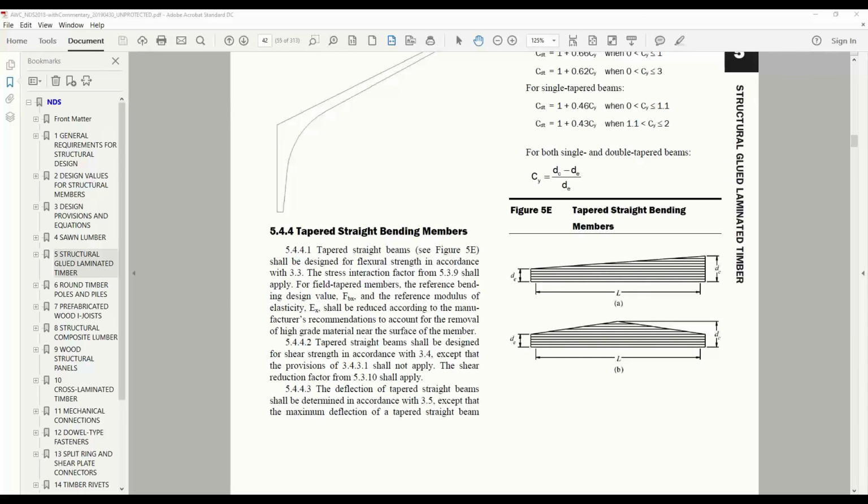Well, that's one reason for the balanced beam, because the tension and compression plies will be the same. So if you're using a balanced beam, that'll be accommodated there. One option is the software that I mentioned. That will check your positive and negative bending in your beam, installed with the top up. So the software would do that check for you if you're specifying a multi-span or cantilevered application. Otherwise, if you're doing it by hand or you have a spreadsheet, you're going to have to make sure you check the negative bending for that application.